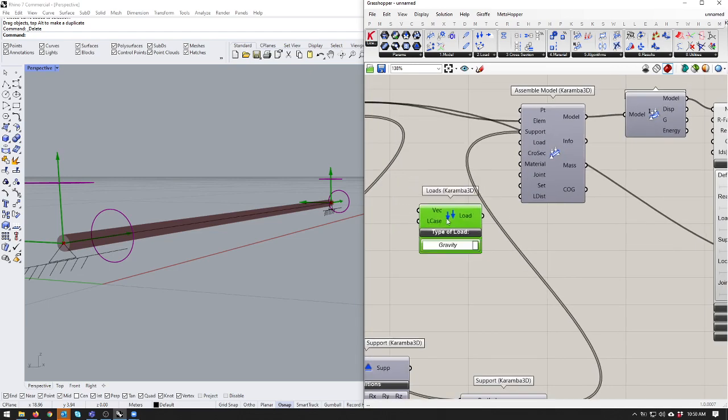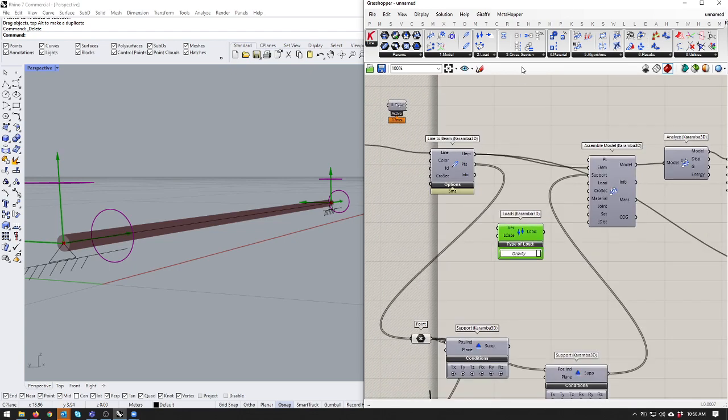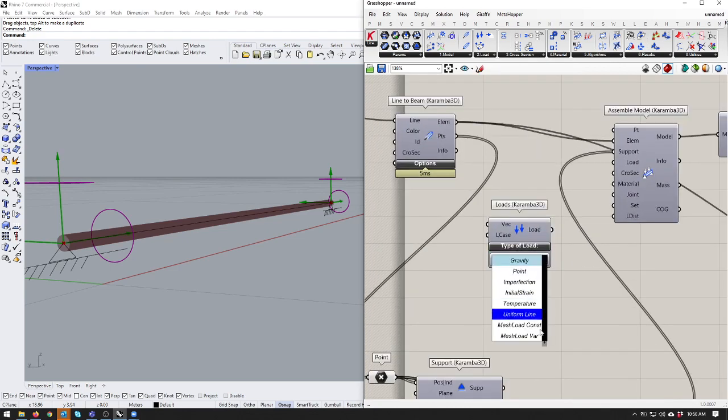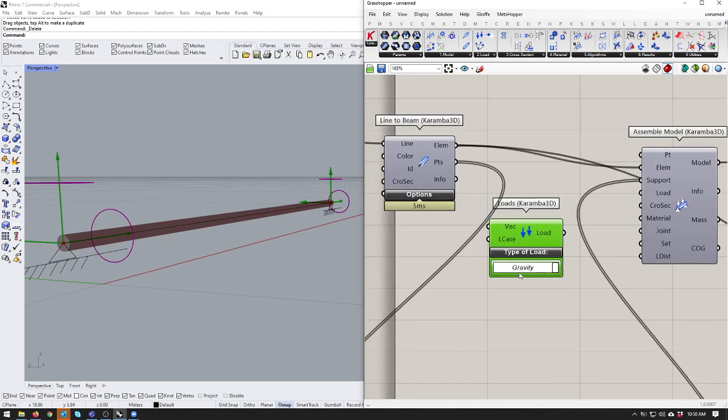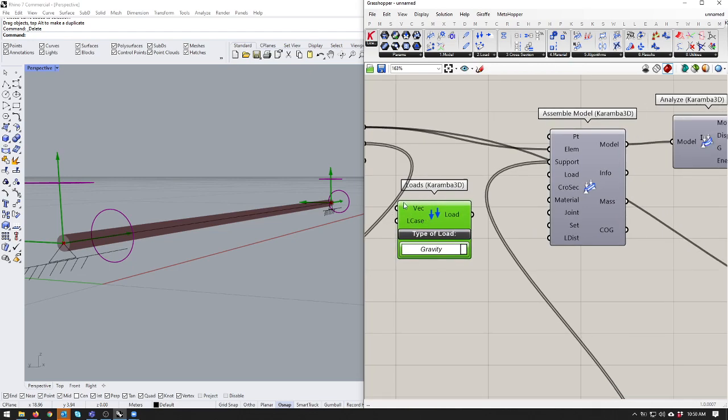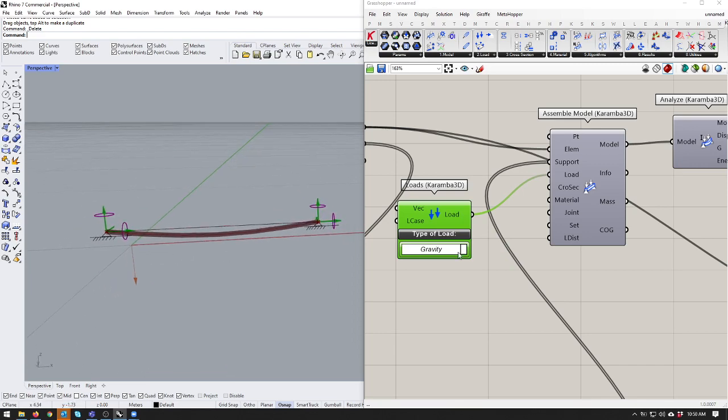So there is this load section. You can find them in loads. Loads has almost all the loads that you care about. So one of them needs to be the gravity load. You basically don't need to plug anything into it. It knows everything it needs to. It's using -1 as a unit of Earth's gravitational force. If you chuck that into the load input, there we go.